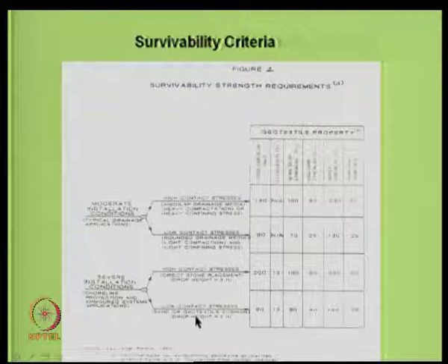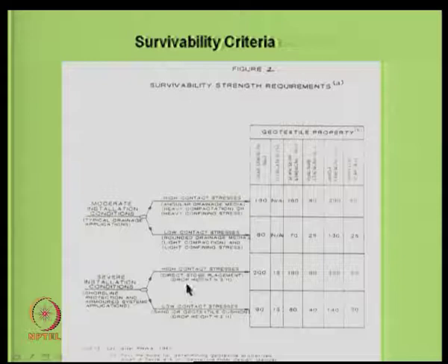There is again a difference here, in terms of the drop of height. For example, if you have a geotextile material, you have to put some stone pitching there. Say you are at a seashore, where erosion is a big problem in many of the sea beaches. If you want to make a nice slope there, what they do is compact a sand slope, then put a geotextile and a stone pitching on top.